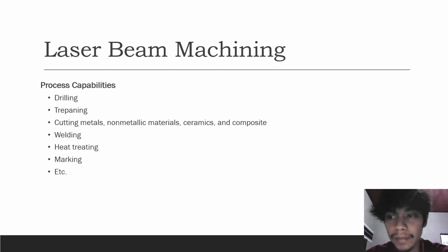Laser beam machining. In laser beam machining, or for short LBM, the source of energy is a laser, which focuses optical energy on the surface of the workpiece. The highly focused high density energy source melts and evaporates portions of the workpiece in a controlled manner.